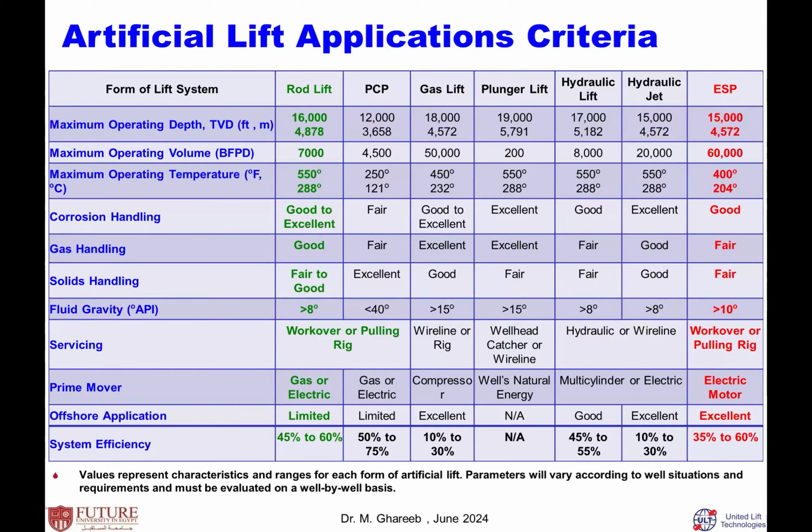One of the challenges for this type of artificial lift is that it usually requires workover rigs in case of a downhole failure, because the pump is connected to the tubing string. In order to pull and run this tubing string, you require a rig. From the name, it uses an electric motor as the prime mover to drive the pump. For offshore, there is no heavy equipment at the surface.